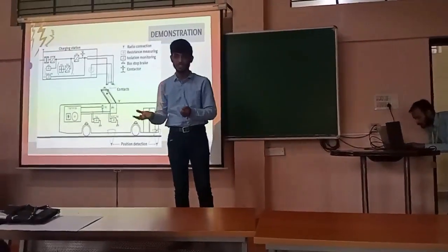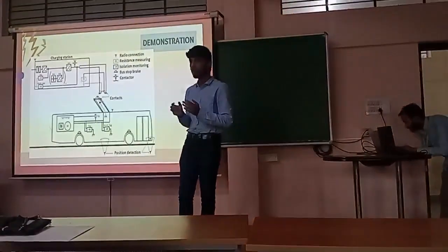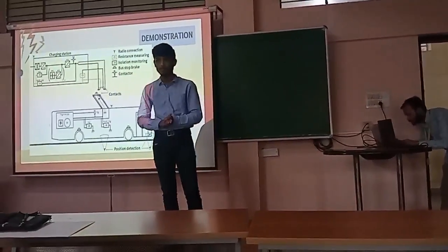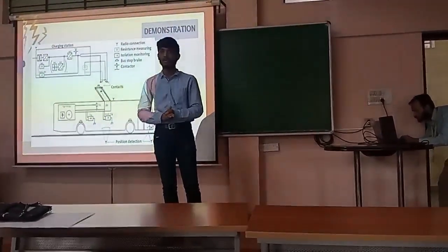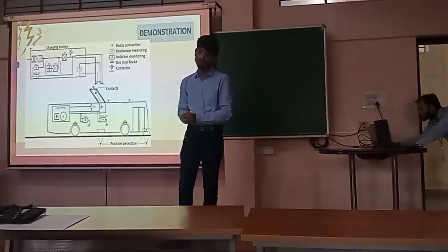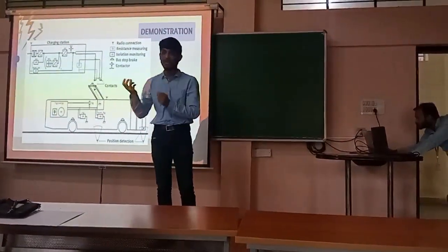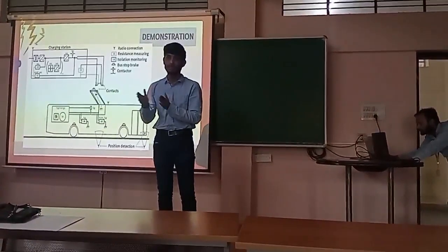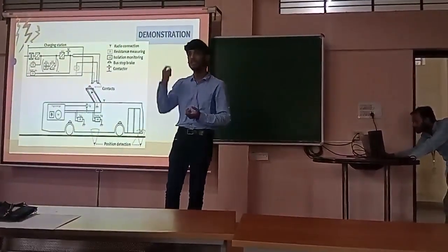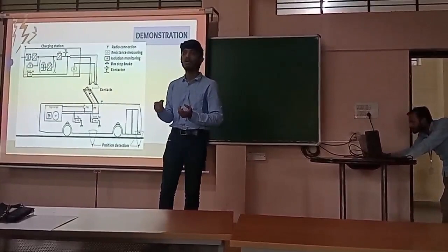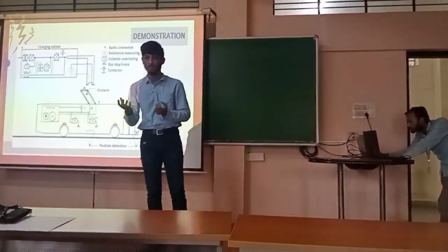Lithium-ion batteries are very expensive and they are hazardous. So we use ultra capacitors here. Capacitors don't come in such a high voltage. Yes sir, we stack them up, like batteries, in series and parallel combination, so that we can get the optimal voltage or the energy capacity that we require.